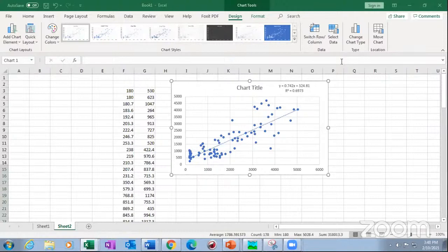In the surface water, you can compute the surface water runoff using HEC-HMS, and then give it as an input: the total volume of water generated from the rainfall. Whatever volume you have, you give that as an input to the conjunctive model, and you can get that input from HEC-HMS. That's the first thing.